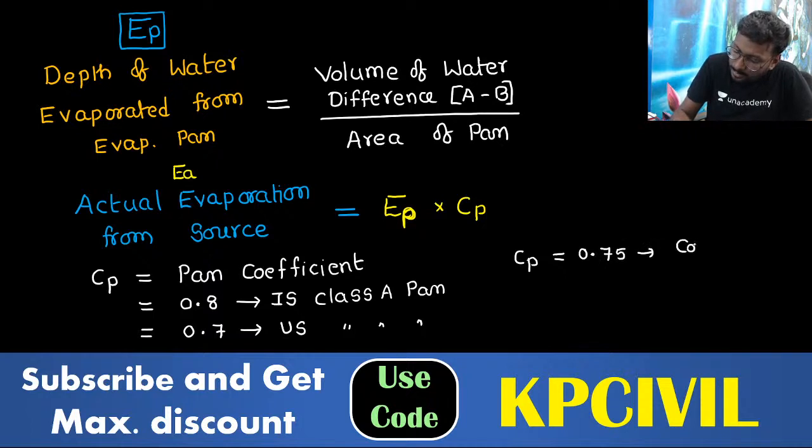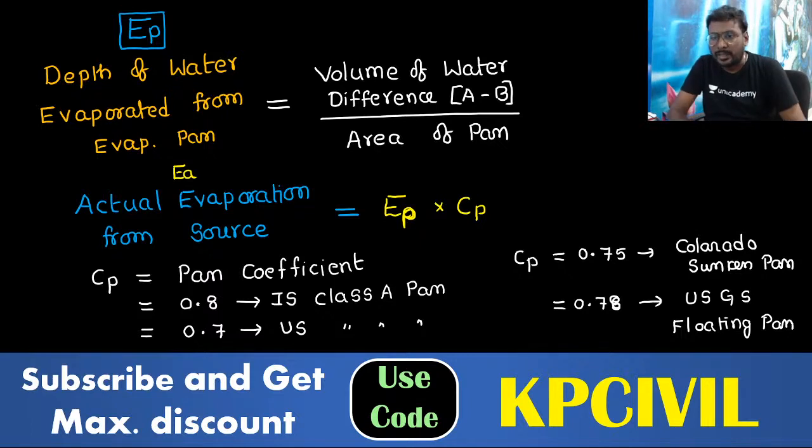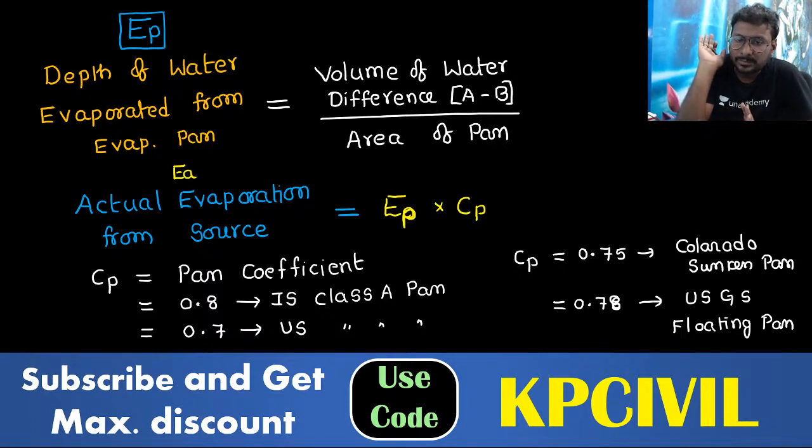Again, pan coefficient is 0.75 for Colorado sunken pan. For Colorado sunken pan 0.75, and 0.78 for US Geological Survey, USGS floating pan. USGS floating pan, pan coefficient 0.78. So depending upon what type of pan you are using, you can multiply pan coefficient.